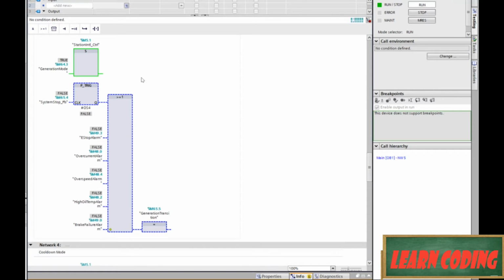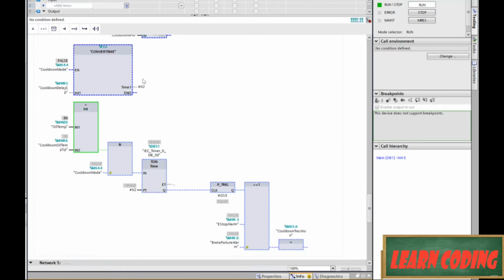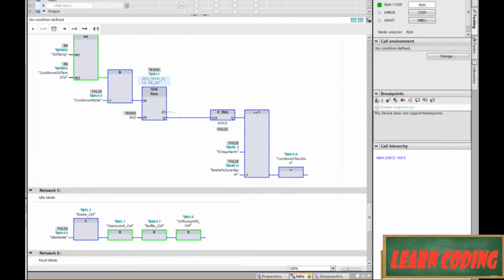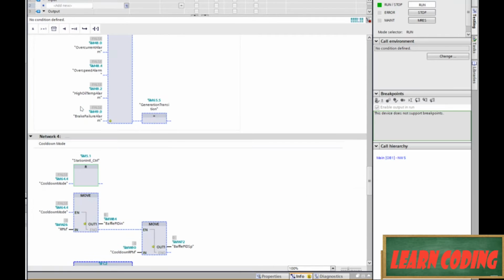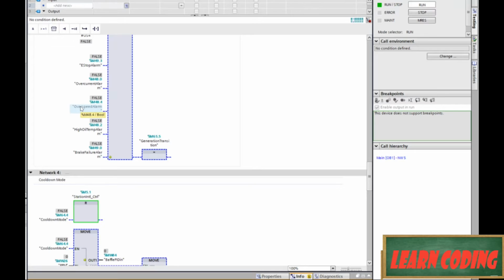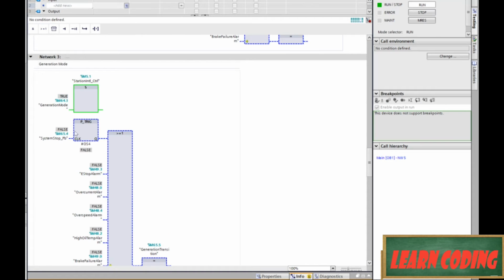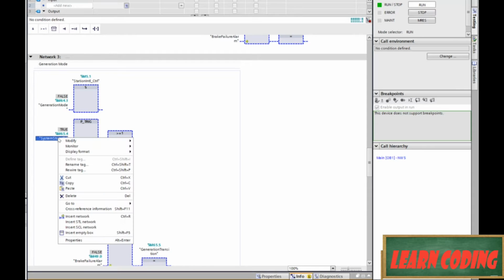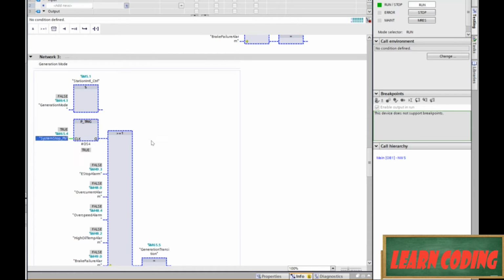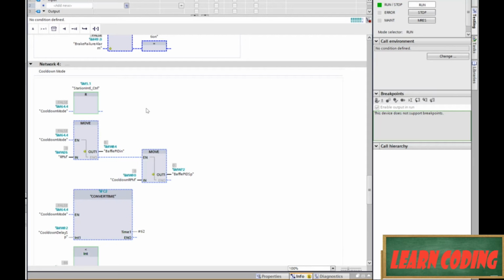and just like that, we've got our interlock control set, and we're waiting until somebody hits a stop button. And for cooldown, we're going to look for our oil to be below 90, and that's not a problem right now. So let's go ahead and toggle our stop button. We instantly left. Now we should be in cooldown, and we're not in cooldown. What happened here?